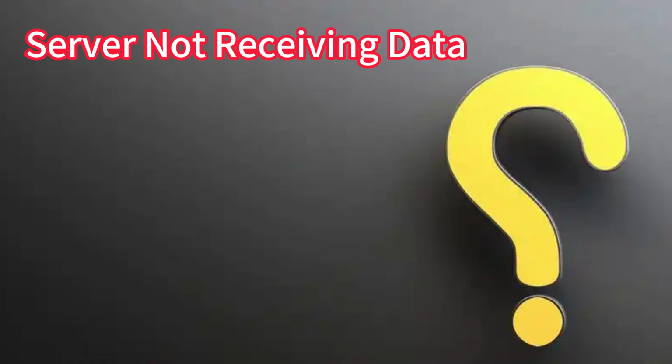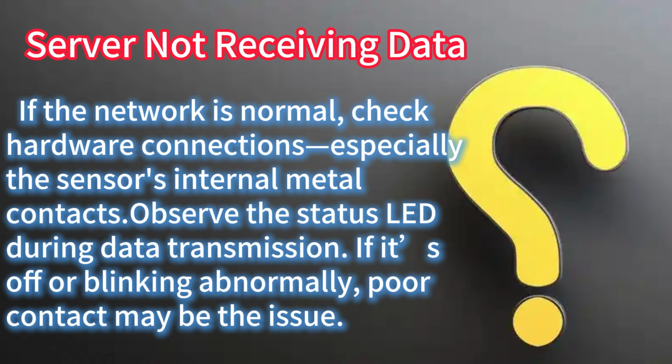Server not receiving data. If the network is normal, check hardware connections, especially the sensor's internal metal contacts. Observe the status LED during data transmission. If it's off or blinking abnormally, poor contact may be the issue.